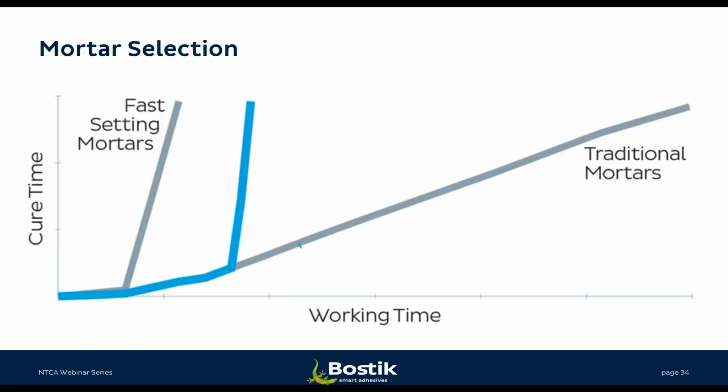So a quick bit about the mortars and the way the mortars have caught up a little bit is that historically when we looked at mortars for the gauge porcelain tile installations, we started looking at fast set mortars, but found out that they were really too fast. They end up curing so quickly that they skin over at the surface before you can actually embed on the floor and or wall, and definitely more challenging on the wall applications.